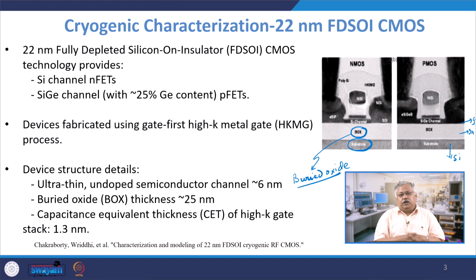Why is it so? Because if you remember, NFETs have electrons as the majority carriers, and since electrons already have a large amount of mobility, the overall current is typically large. So if I have an SOI based NFET with a silicon N channel MOSFET, then its current is, suppose, X. However, if you take everything the same for a PFET, the mobility being relatively smaller, you will always get a smaller amount of current for PFETs, right?